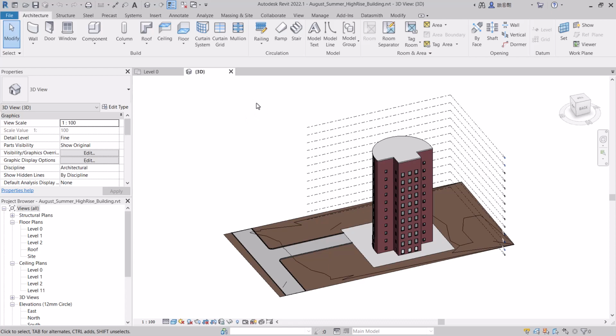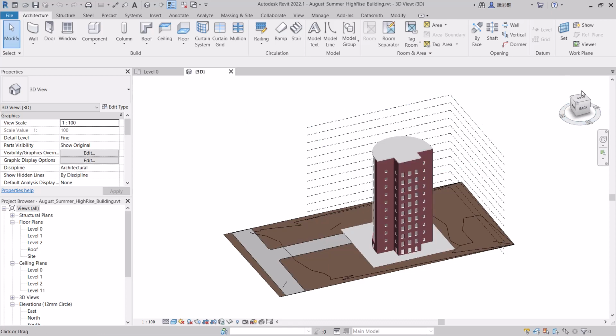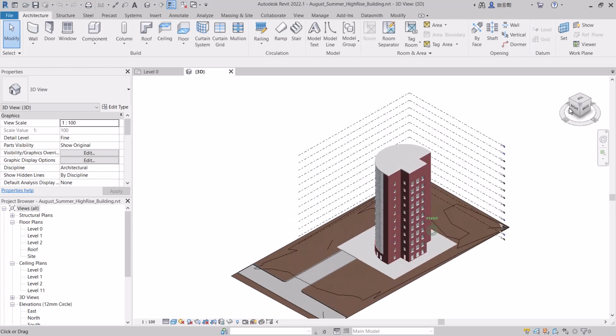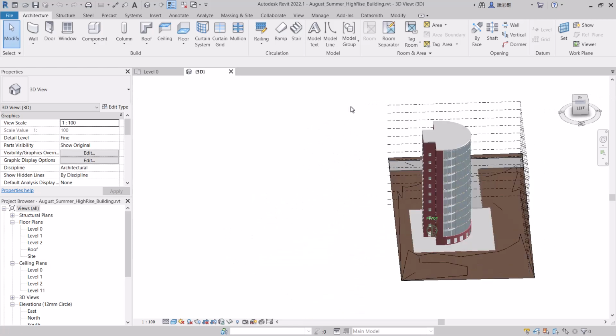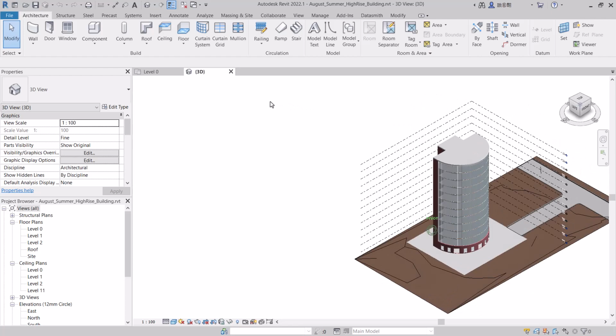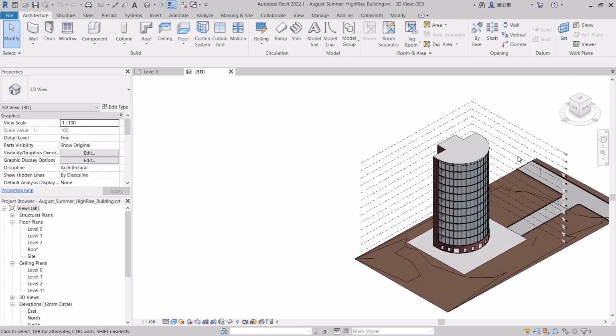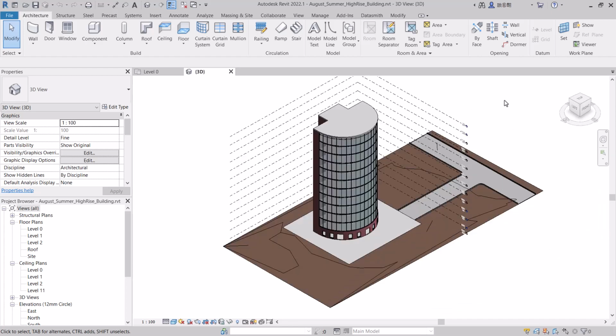And there are two ways you can actually go about doing this. You can choose to export a 3D version of the file, or you can choose to create a direct link that links directly to Twinmotion, and then any edit you make in Revit can automatically be synchronized into Twinmotion, and then you can go on to edit your building and your model and visualize your model simultaneously like that.